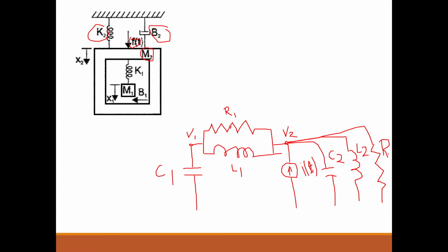Our diagram is over. Electrical analogous circuit we have drawn. Now join other terminals, and you can draw a reference node anywhere. All the other terminals of these elements will meet at the reference node. You can draw a reference node and mention node voltage as 0 volts.